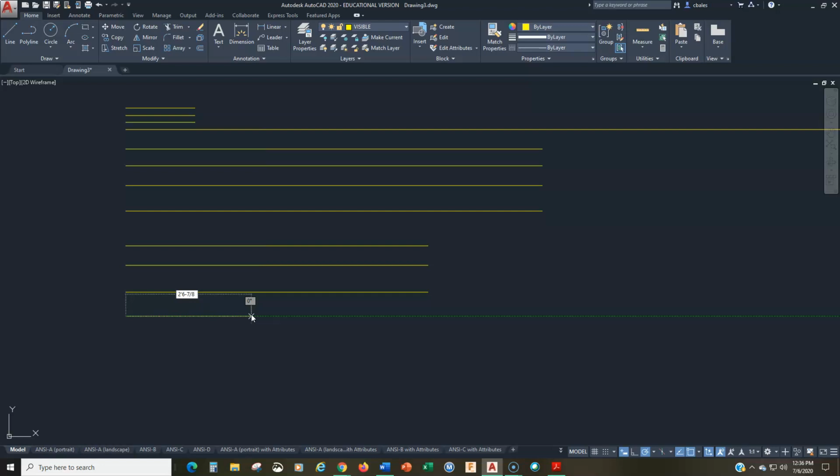Now notice here that I'm putting in fractions that are less than or more than 1/2 inch, right? And my precision was set at 1/2, right? That's still fine, right? Notice what it does when I look at the distance though. It only displays to a 1/2 inch precision. So what happened?